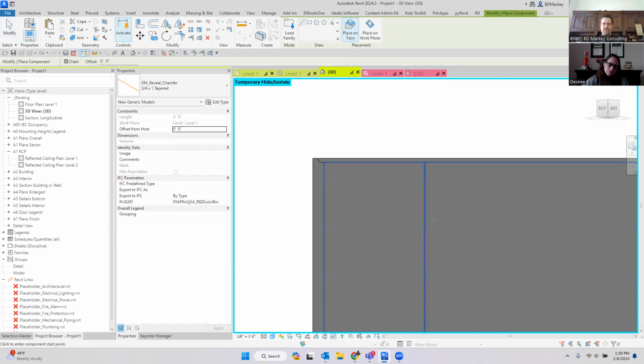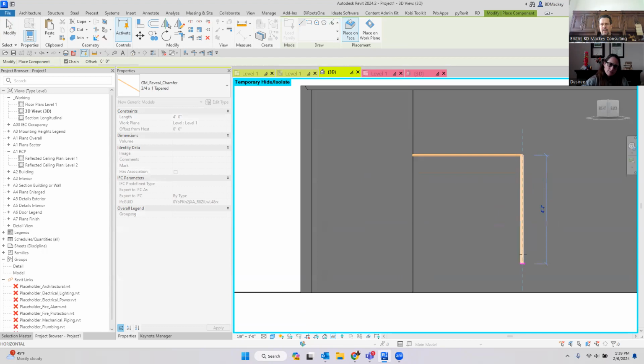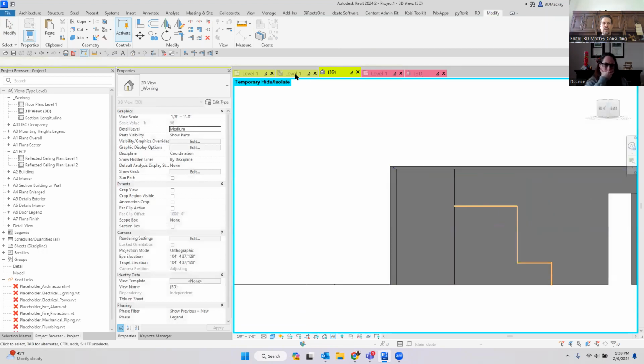Make sure I'm still faced. Right, so now I could do whatever I wanted to do with this reveal family. And then I can use the cut command. Check multiple cuts here. Grab the wall and this and this and this and this.